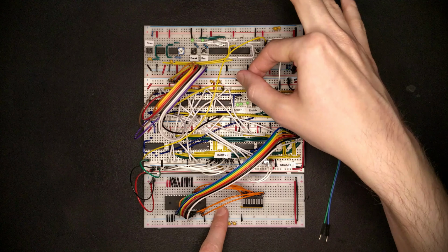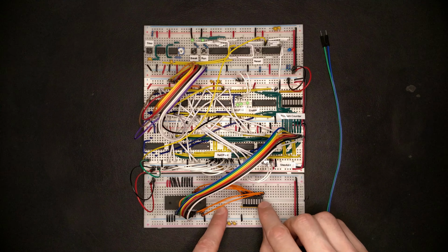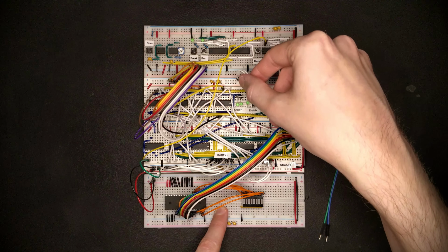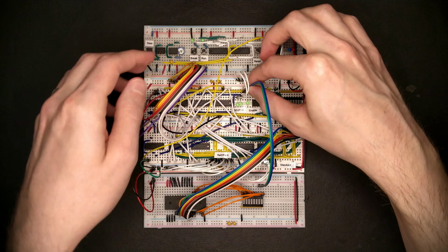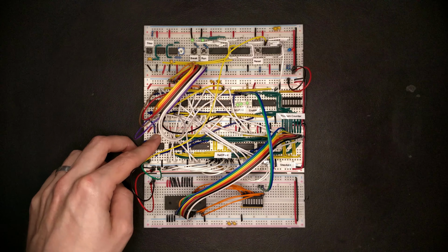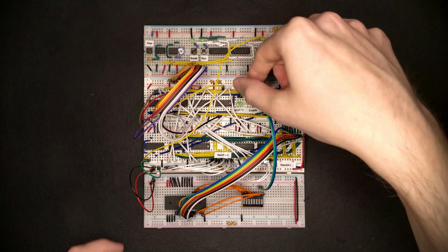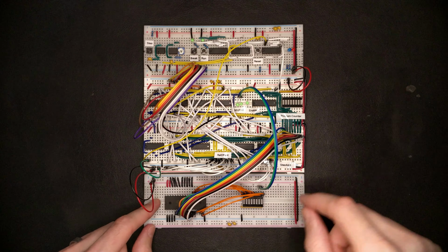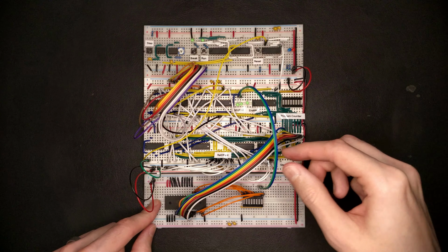First, let's look at the select line here of the program counter. And let's use bit 0 and 1 of whatever comes out of the memory to drive these signals. So this basically allows us to configure the lower 2 bits of whatever is in memory, and this will control what the program counter does at that point.